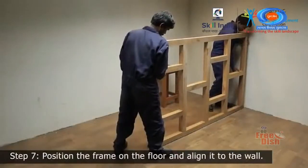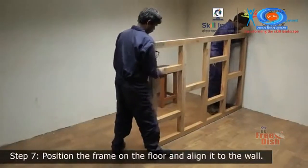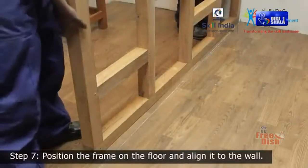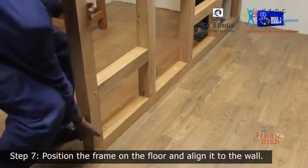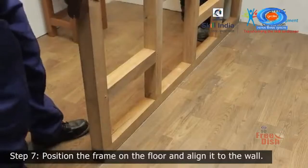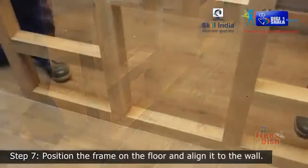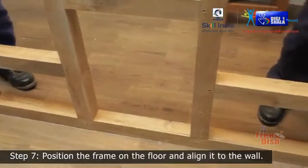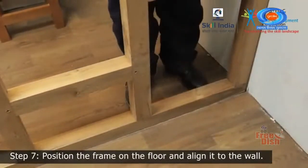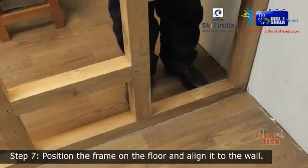7. Position the frame on the floor and align it to the wall. Place the partition frame on the chalk line. Ask a helper to lend you a hand. Position the frame so it sits flat on the marked line and perpendicular to the wall. Once in place, check if the frame is held straight against the wall.